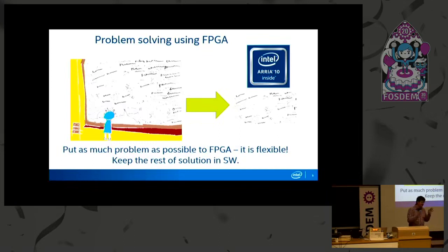We implemented very, very good multipliers in the hardware for the data, and what we saw was that software alone still works faster than software plus hardware, yes? Why does this happen? It happens because the killing factor was moving the data between the software and the hardware over the PCI. Our hardware is connected to the card through the PCI, yes?